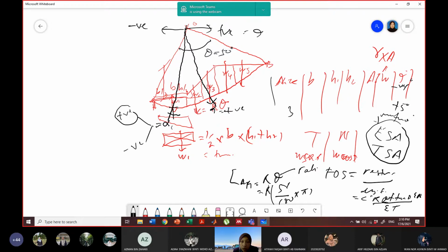The most important thing is that you have to be clear on how to draw the slip circle, and then know how to get H1, H2, area, W, alpha, and the last ones, T and N. Okay, do you have any questions on last week's topic, slope stability calculations?